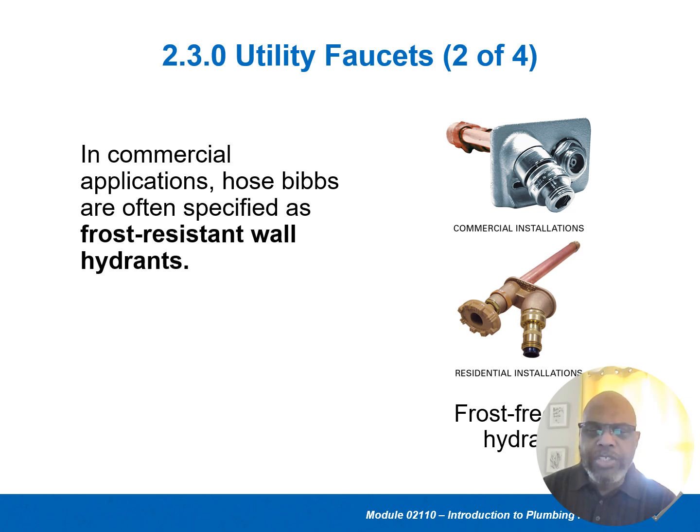So it has an extension piece inside of the wall that goes back between 10 to 12 inches. It's just in case it gets extremely cold outside, the temperature will not cause that valve to freeze with water in it and crack the pipe. So it has an extended seat in it that goes back between 10 and 14 inches inside of the room instead of at the valve itself. And in houses, it's actually installed also, so that hose bibs do not freeze in low temperatures outdoors.